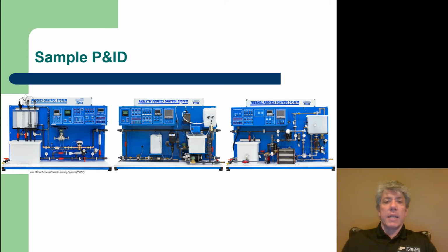And I designed mine to go sort of in between the 52 and 53. The 52 and 53 were originally designed, you can see the pipe stubs there, to just screw in together so you could have the two together and learn to control temperature and flow and level all at the same time. And mine's designed to go in between those two systems and control pH while you're controlling everything else. It flows in a generally counterclockwise setup, so you could have any one of these individually, just cap off the stubs at the end and have counterclockwise flow.